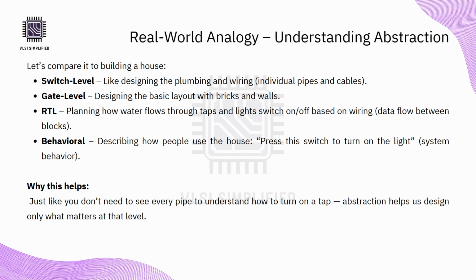And finally, the behavioral level. This is like saying, when I walk into the room, the light should turn on. So we're only focused on the expected behavior, not how it happens internally. Abstraction in Verilog works in the same way. Every level hides unnecessary details so you can focus on the logic that matters at that stage.